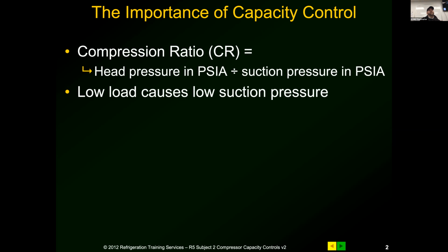What that does over time is that refrigerant is still absorbing heat inside of that compressor. It's absorbing heat through the body of the compressor, and then it's absorbing heat in that heat of compression. So if you have less new gas in there, you have less heat absorption. Over time, as that piston's going up and down, it's not absorbing enough heat, and so it begins to overheat the compressor. That's really what it comes down to, and that's why compression ratio is so important. It's telling us that we have a good measurement of new cool gas being introduced to each cylinder stroke.